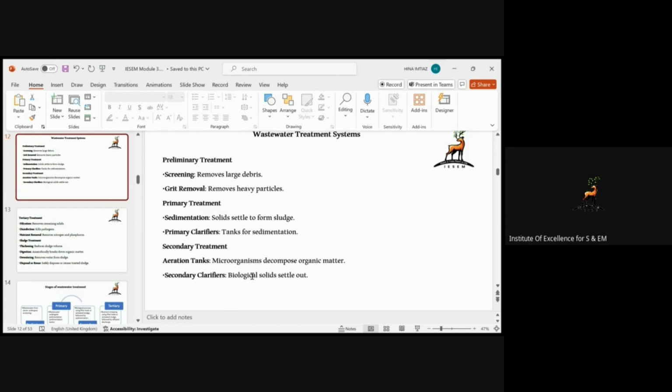microbes, so that the microbes will help to decompose the organic compounds and the contaminants which are toxic for the environment. Aerobic means those bacteria which can use oxygen to break down that particular contaminant. Where the word is aerobic or aeration, you will have a clear idea that it is the involvement of the air, the involvement of the oxygen. So basically, the aerobic bacteria use that air, that oxygen, to degrade and decompose that particular contaminant.